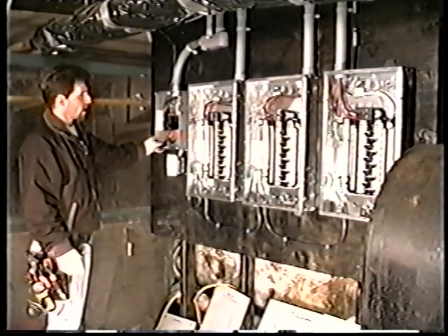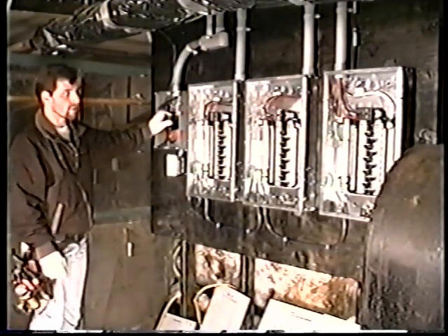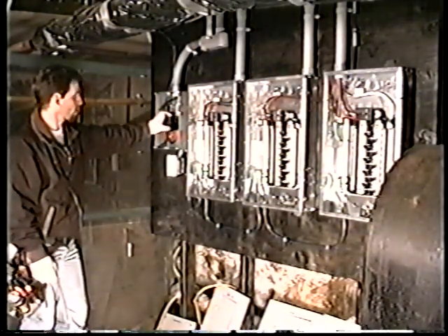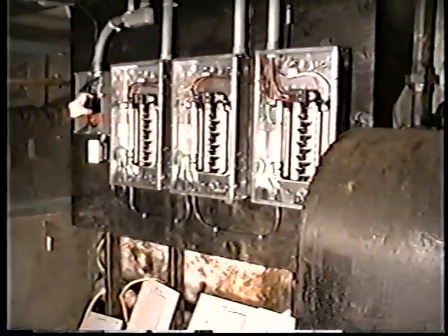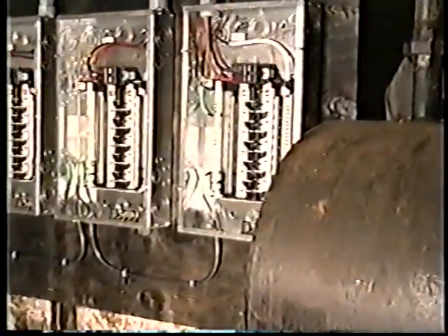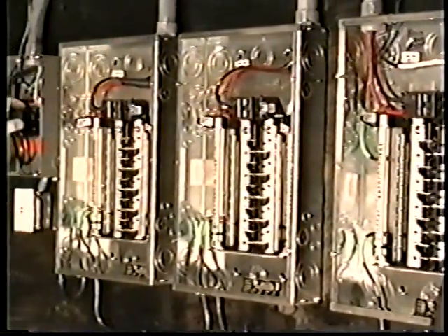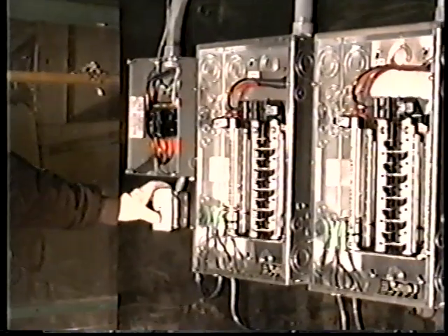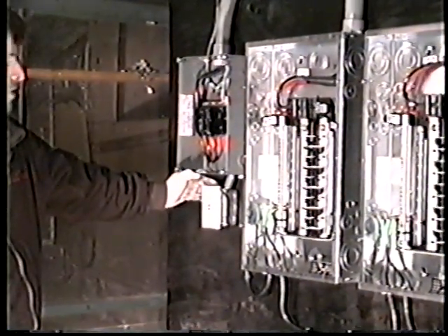And this is a modern day panel. This has all circuit breakers. Everything will be controlled on a circuit breaker, no fuses, and you can't upgrade the size without removing the breaker and putting a bigger one in, which most people won't do. So this is a much better system. It's a lot safer. It's new, and we also have to have one general outlet in the area, and you have to have illumination in the area of the panels also.